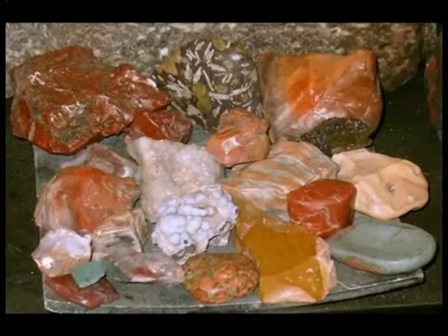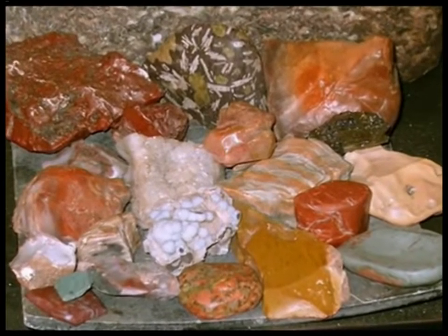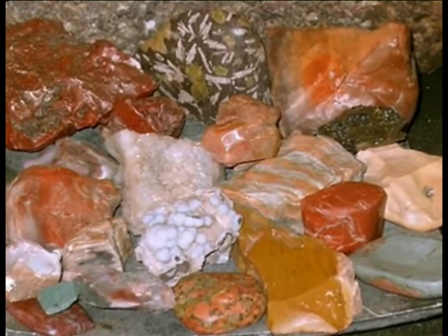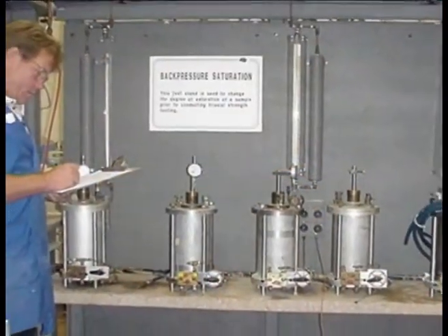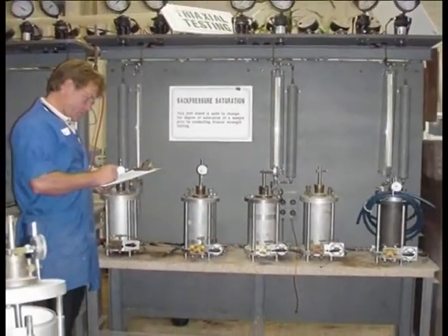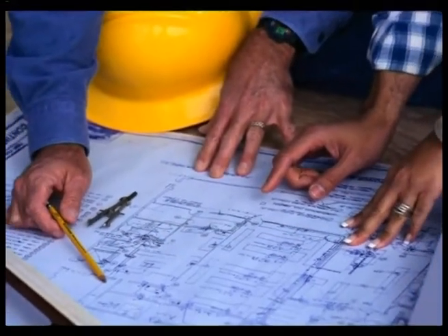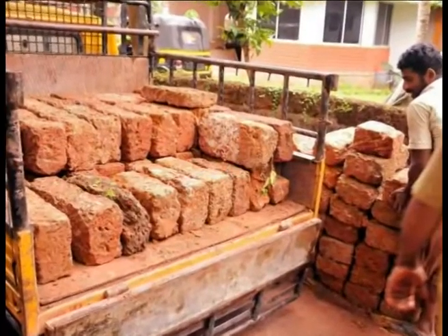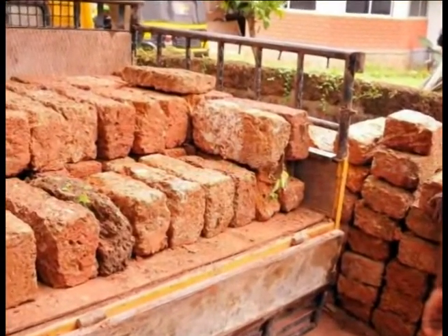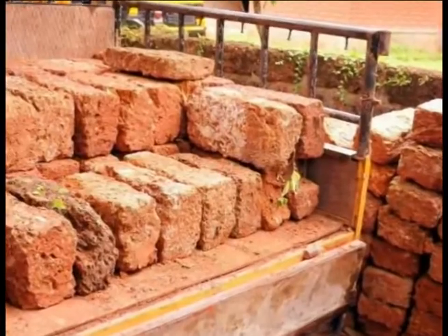The carbonate rocks show a wide variation in their properties, and particular deposits of these rocks have to be tested by taking random representative samples before the stone is recommended for use in engineering constructions. The presence of some minerals, even in small quantities, is to be viewed with caution while utilizing building stones. The minerals are mica, gypsum, sulfides, tremolite, flint, chert and clays. These destroy the inherent strength of the rock.